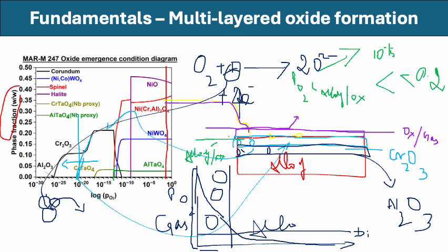And if we can predict what kind of oxide layers will form, then I can optimize the conditions to promote or perform some pre-treatment. For example, if you do some argon pre-treatment, argon inherently has a lower oxygen partial pressure. You might go to a condition where you can promote this chromia directly, which grows slowly, rather than directly putting your alloy into service without doing some pre-treatment.